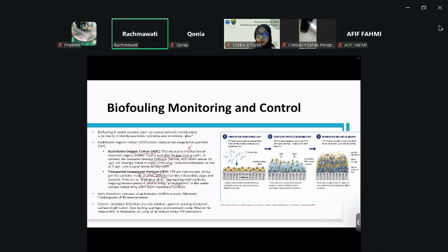Yeah. Now, how to control it? You have to keep in mind the substrate limitation: you have to know what kind of membrane you are using, and compare it to the contents of the feed solution, and also the biocide rotation or quorum sensing disruption. Probably surface modification if you want to modify the membrane, and also pretreatment using filtration like ultrafiltration or microfiltration to reduce the sticky transparent exopolymer particles. So for example, this is the TEP, the gel-like polysaccharide.